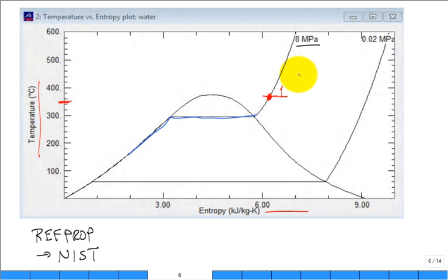It's superheated vapor. State 2, straight down, you do a reversible expansion, isentropic flow through the turbine, and state 2S will be right there. But because they said it was isentropic efficiency of 70%, state 2 actual with a dashed line will be somewhere like that. Why do they put a dashed line on the property diagram like a TS diagram? Because it emphasizes that it's an irreversible process. What does a solid line indicate on a property diagram? Reversible.